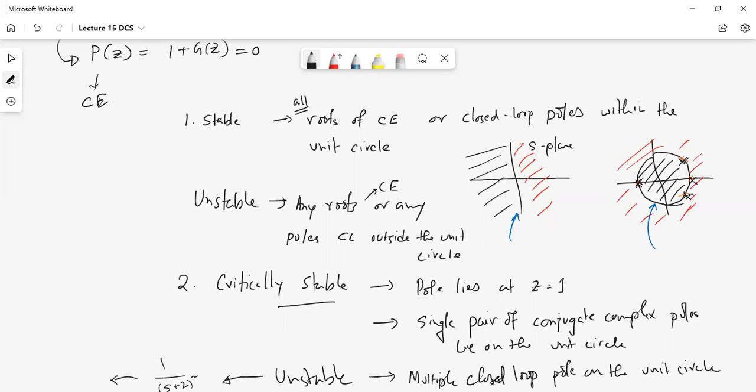If you take it to the time domain, you're going to see that it will be t e to the power minus a t. This t term makes the system go to infinity as t goes to infinity. So the magnitude tends to infinity, and that is why the system becomes unstable.